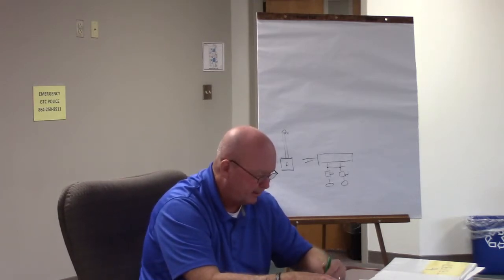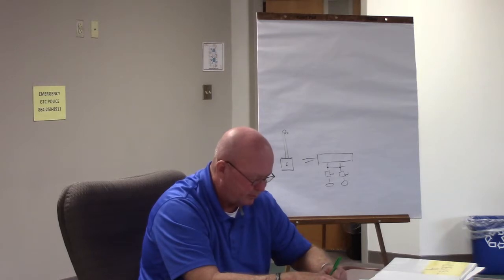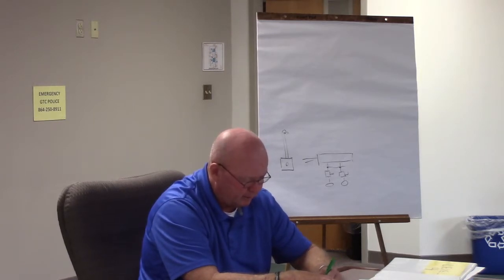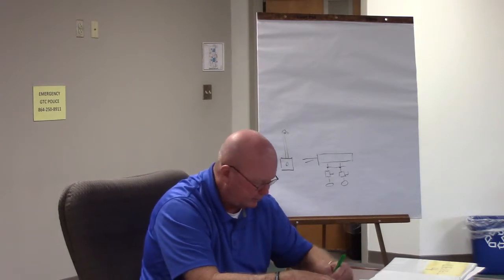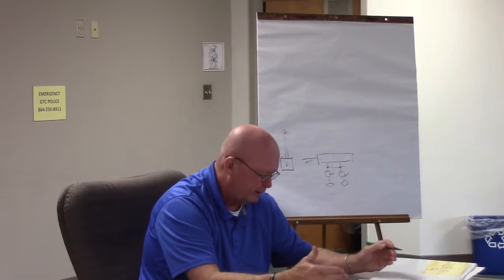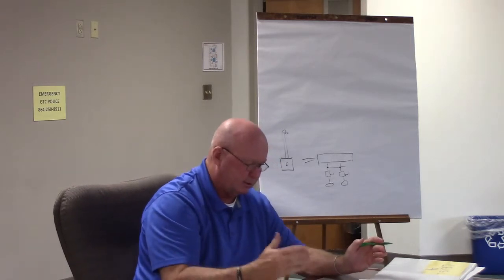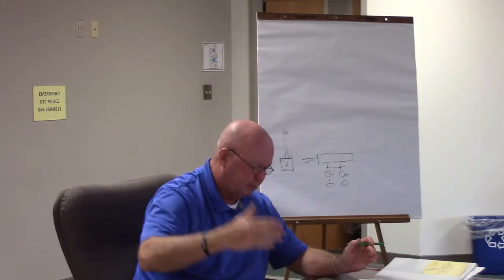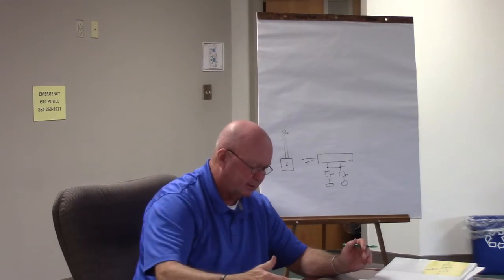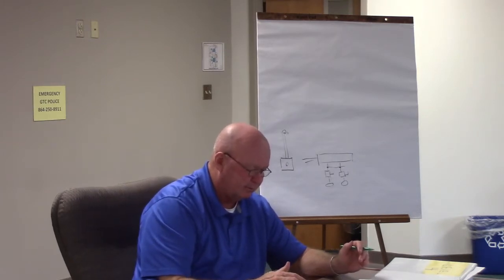Service point and point of connection. Service point is our first two blanks. Point of connection. Okay. So overhead service conductors go between the service point and the first point of connection to the service entrance conductors at the building or other structure. Okay. Does that make sense?